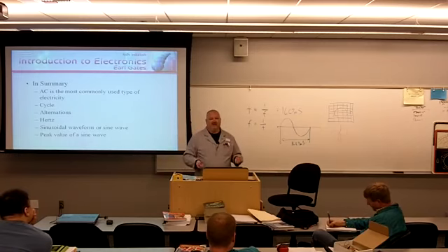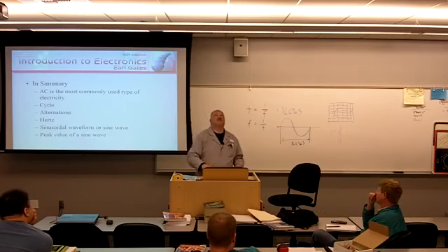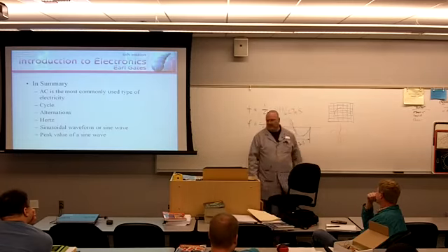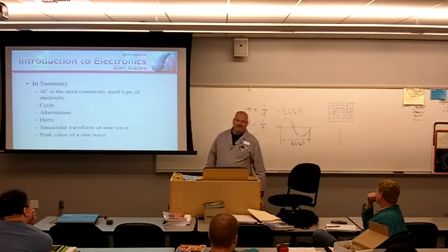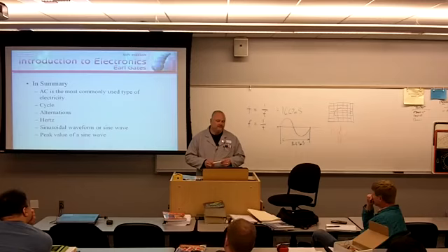And by having that connected like that, I look at the computer and then immediately patch it up to the oscilloscope. Look, circle. Yeah, the computer's not lying to me. Or, no, I'm getting one of these. The computer's lying to me. This isn't even the frequency that we're at. It's lying to me. I could discount that and then move on. It's called a Lissajous pattern on the oscilloscope. And I'll show you in the lab someday how to do that. It's kind of cool.